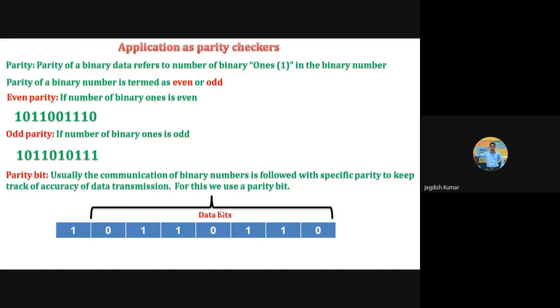This may be data corresponding to some number. This may be data for anything, right? So you fix some bits in the binary data, and those are called the data bits. And we fix an additional bit to the left of that binary data, and we call that bit the parity bit.